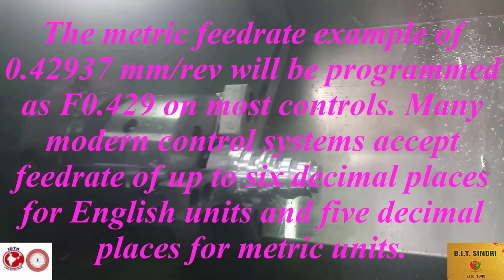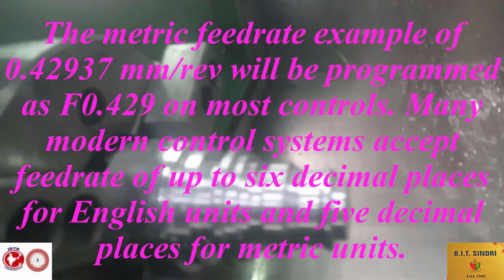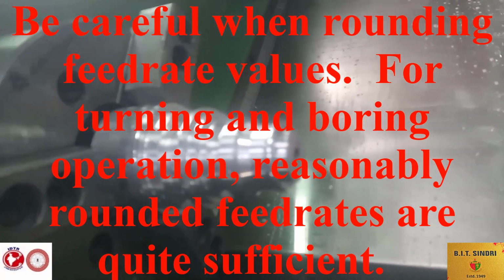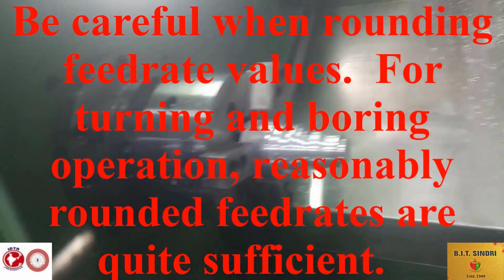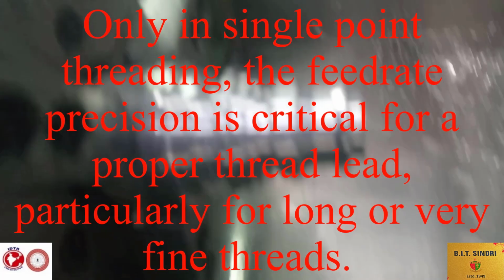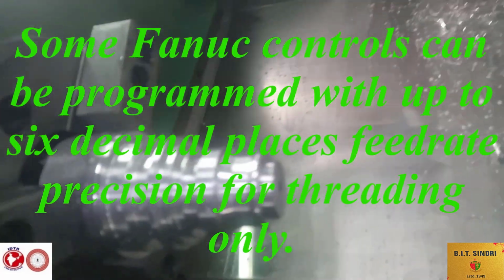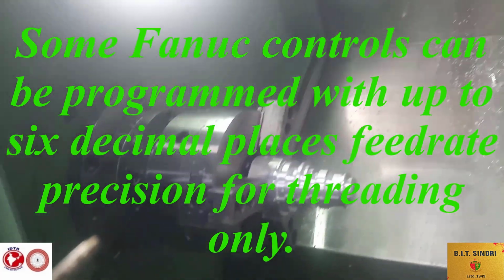The metric feed rate example of 0.42937 mm per revolution will be programmed as F0.429 on most controls. Many modern control systems accept feed rate of up to 6 decimal places for English units and 5 decimal places for metric units. Be careful when rounding feed rate values. For turning and boring operations, reasonably rounded feed rates are quite sufficient. Only in single point threading is the feed rate precision critical for a proper thread lead, particularly for long or very fine threads. Some controls can be programmed with up to 6 decimal places feed rate precision for threading only.